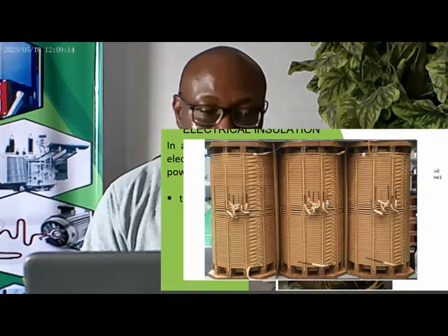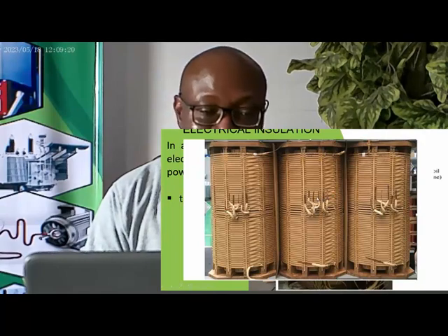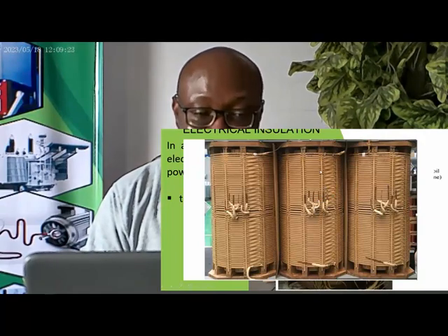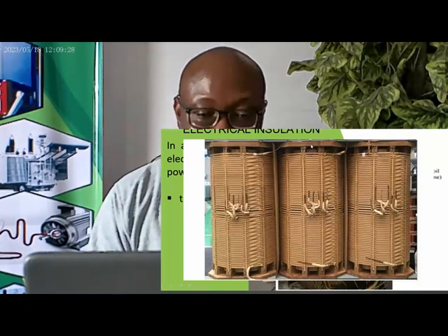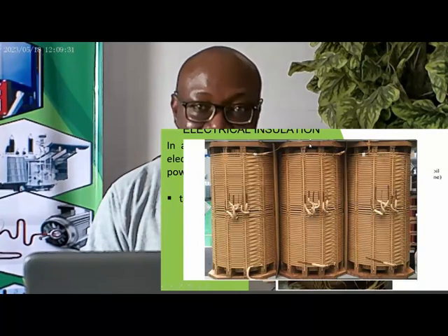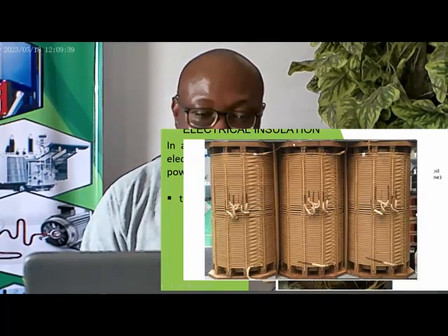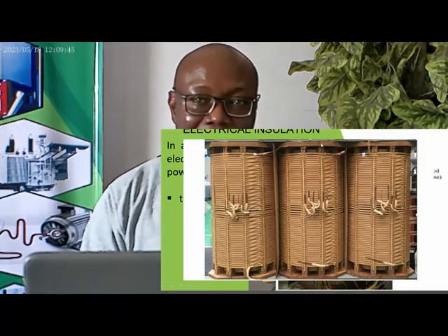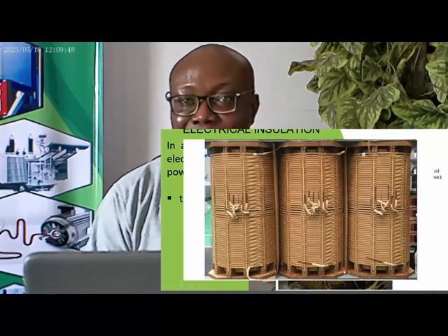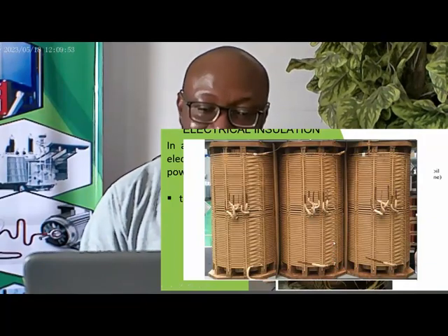So you see the primary winding and the secondary winding; remember from what we saw, they do not have interaction. So when you test the insulation between these two, you expect it to be very high, because they don't have any interaction. And also remember the core of the transformer was insulated before the laying of the first winding on the core. So you see that this winding will not have any business with the transformer core. Are you getting it? None of the windings has business with ground of the transformer, as we will see later.